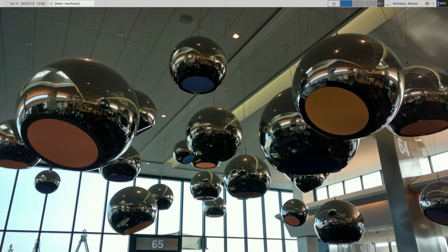Now if I know what the circuit is and I see it, and there's an input labeled A and another input labeled B, and your truth table has inputs labeled A and B, now I can do exactly what you did. I can set A and B to 0 by connecting those to ground. I can write 0, 0 on my truth table. I can look at the output, which is labeled, I don't know, X. And if there's an output X in my truth table, I can say if the LED was off, it's a 0. If it's on, it's a 1.